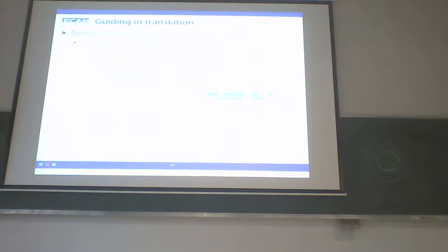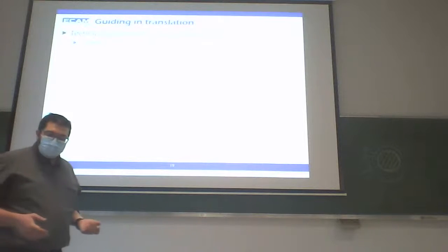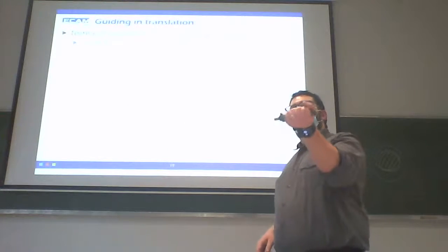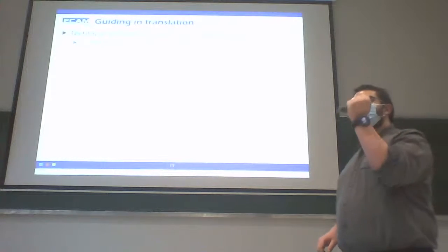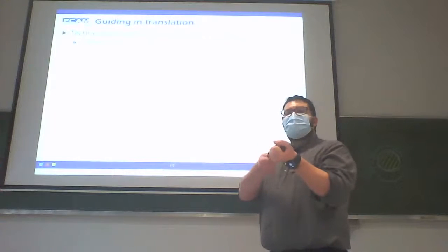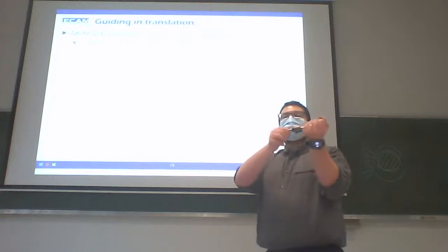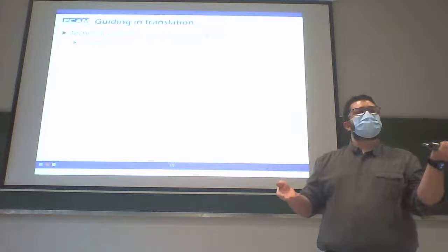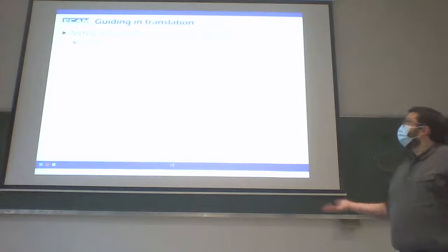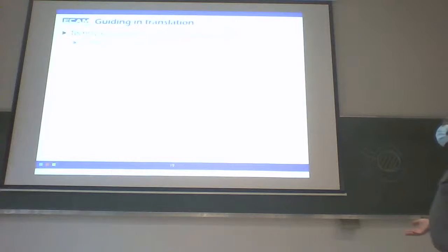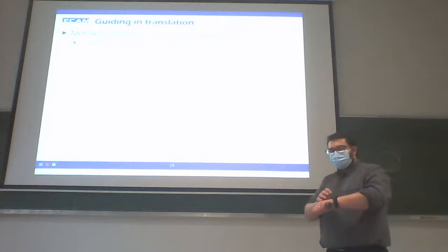First, we can use a cylindrical surface plus a rotation stop. Think about this: when I realize a cylindrical joint, so a cylindrical part inside a cylindrical hole, here I remove 4 degrees of freedom. I only have one translation and one rotation. If I stop this rotation, I only have the translation, so a sliding joint. So to realize a prismatic joint, a sliding joint, I can use a cylindrical contact plus a rotation stop.